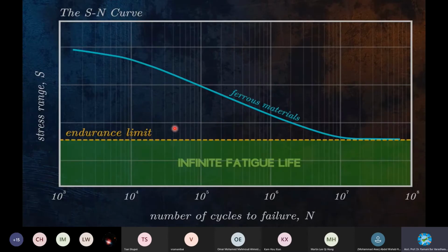Another type, okay, it's a colorful diagram for you. Stress range, taken in megapascals, on this side, and number of cycles on this side, right? In other words, the tolerance limit, the endurance limit, is given. You see here a very high limit of stress it can take.